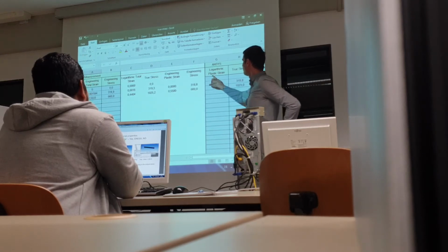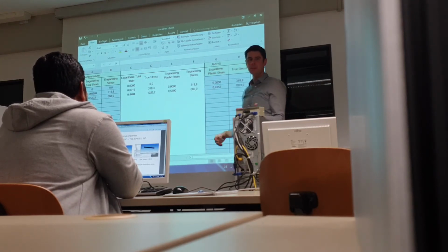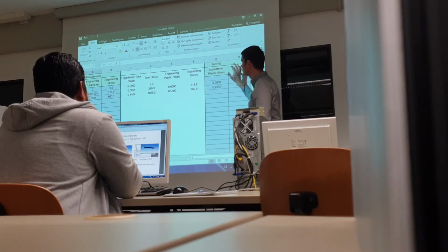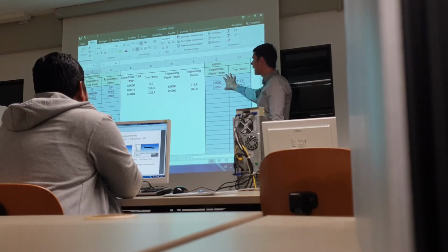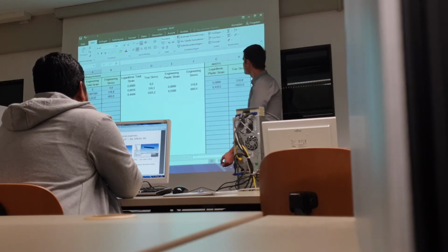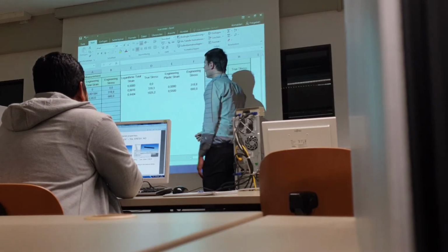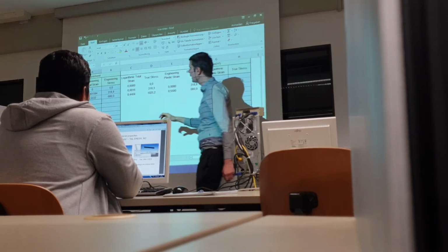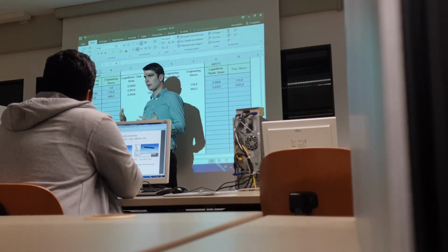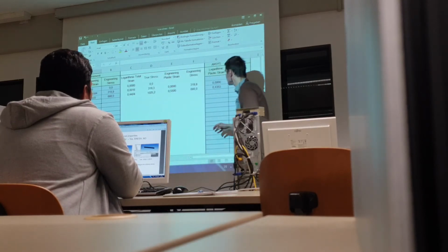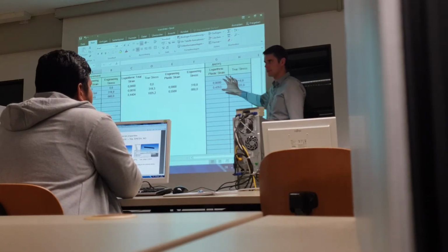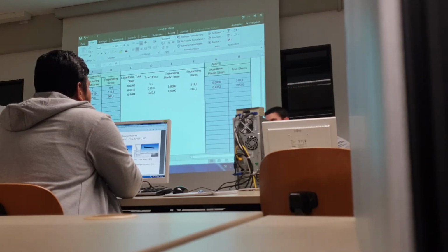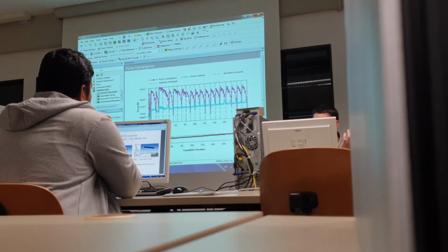But what is interesting is that this is plastic stress, the next problem. The next place to make a mistake, and many people make mistakes here. They think that this line is total strain. But in every software, same story, I need to say separately where the plastic part is and where the elastic part is. The measurement is total strain, plastic plus elastic, and ANSYS and other software want to see the plastic separately. So what do I have to do for a correct simulation?